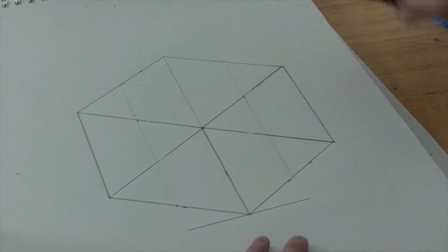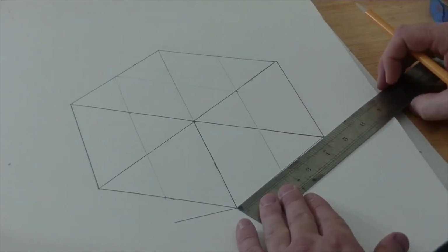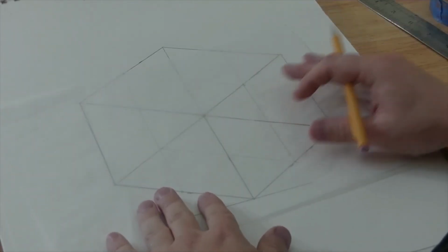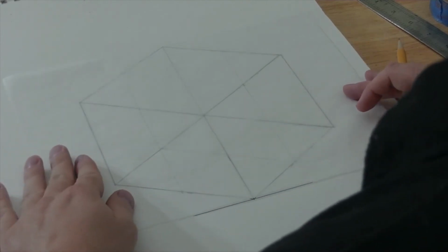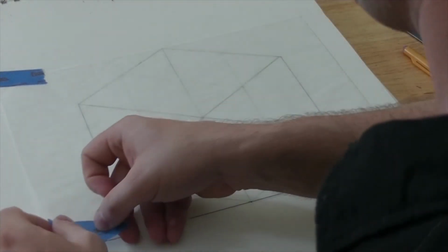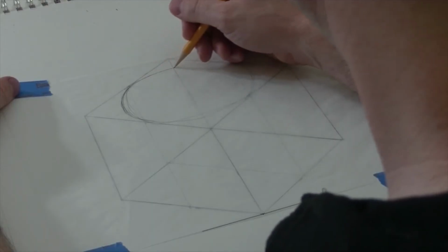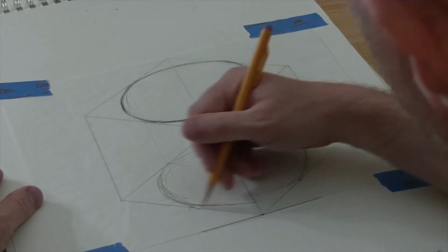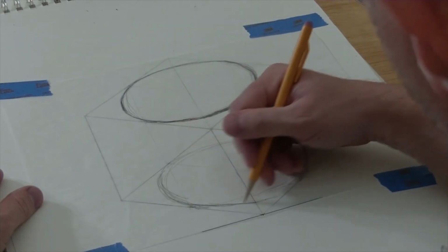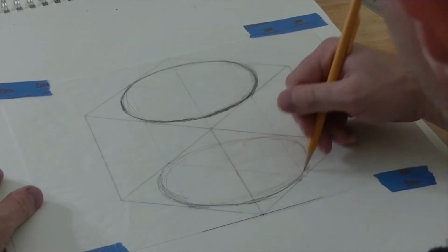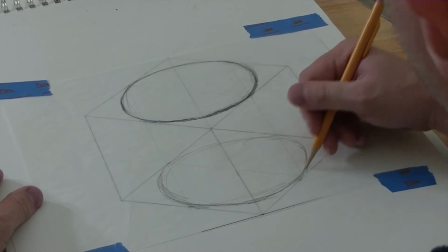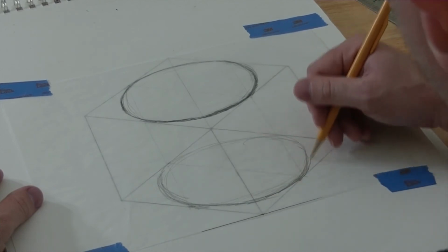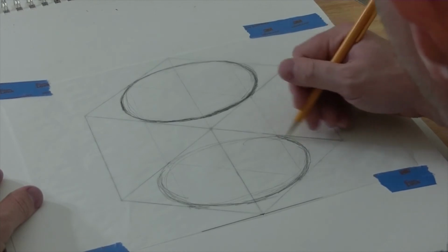And stop. Now that you've drawn the cube, use it to construct a cylinder. To keep things neat, make a new drawing on tracing paper, taping or clipping it down over the cube drawing so it doesn't move. Then draw ellipses on the top and bottom planes of the cube. Make sure they fill the surface by just touching the midpoints on each side, then maintain a continuous curve all the way around with no flat spots, lumps, or pointed ends. Okay, start.